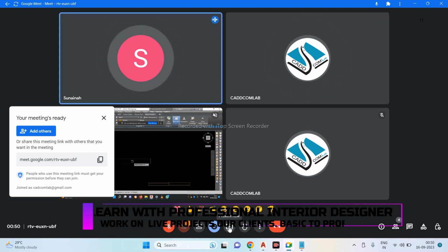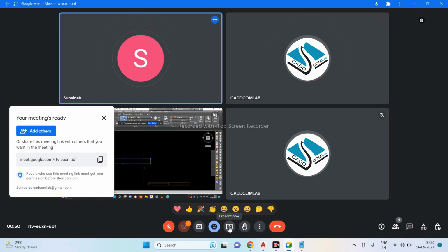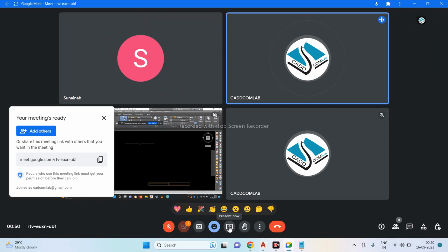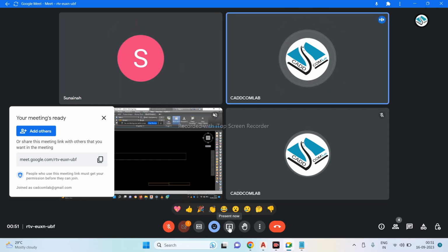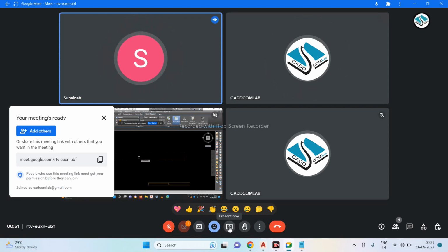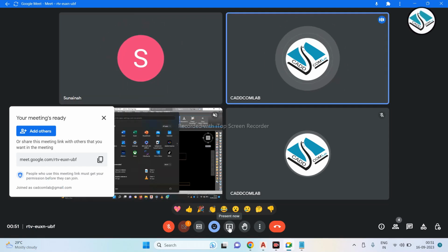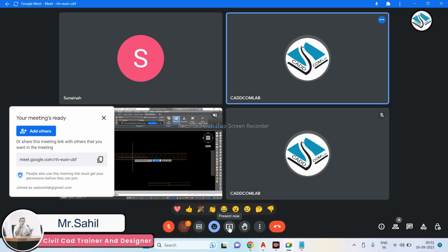Yes, exactly, that's what I wanted to say. Just create any rectangle and then place the hatch in that position. Now place any hatch inside the area. Do not use select objects, just use pick points. Do not use pick object.